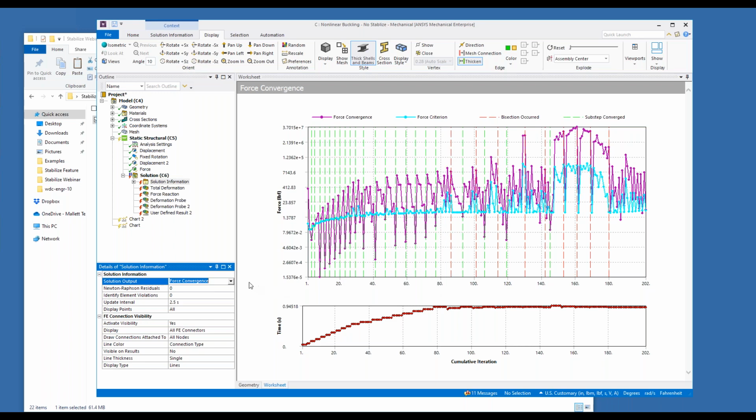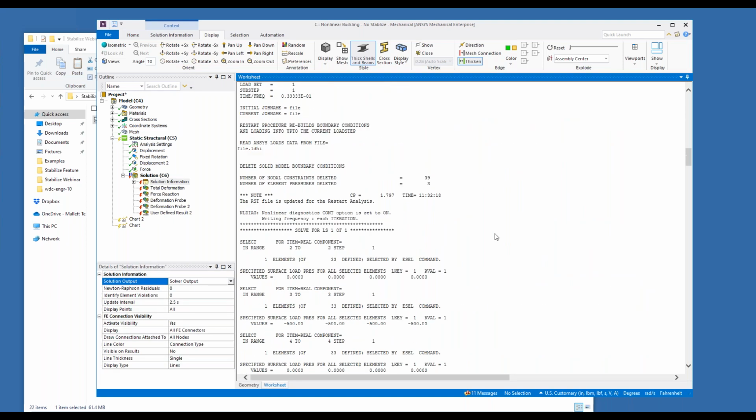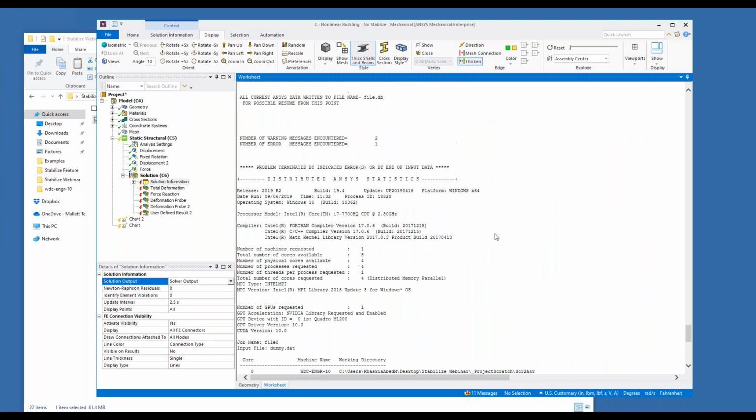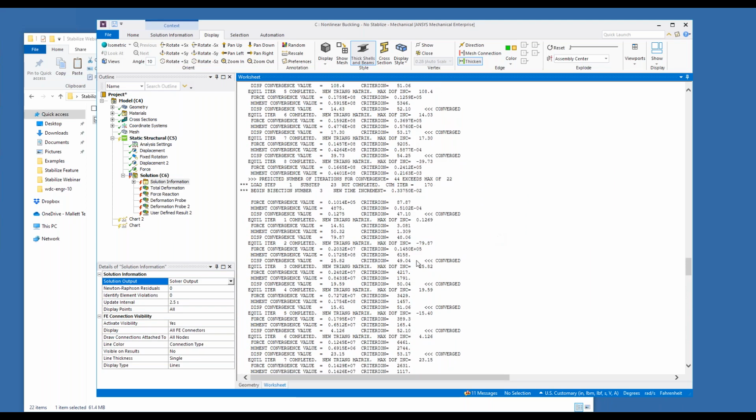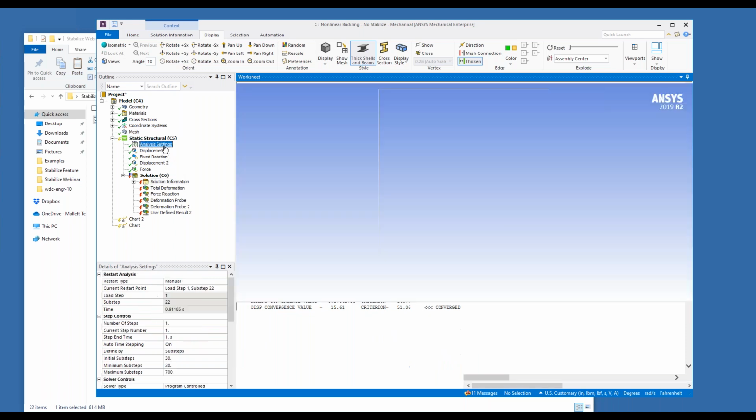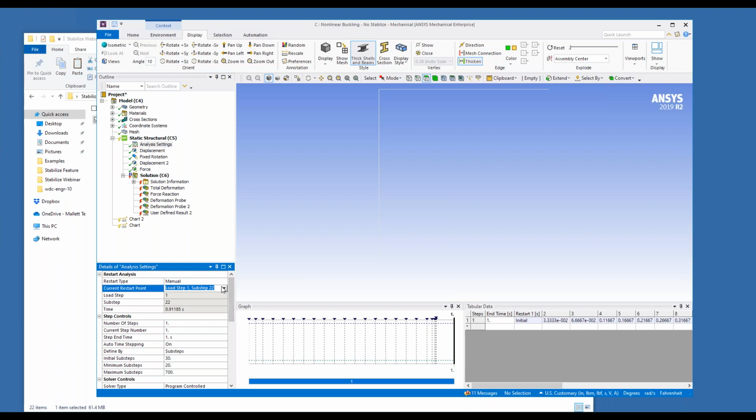And I did track it, believe me, when I prepared my notes here. If you look at this, somewhere just before you start doing bisection, I cannot show it because this is the output for the previous one, at step about 32 or something like that. So if I go back and start my nonlinear analyses here, at the previous step, let's say I'll go 18. So just push it a bit deeper, before the point at which the first bisection started with the code. That's where the instability started in the system.